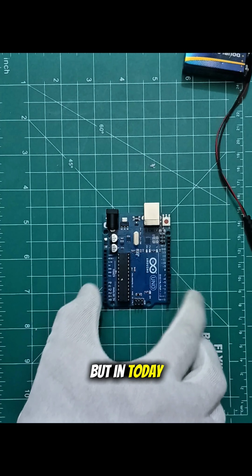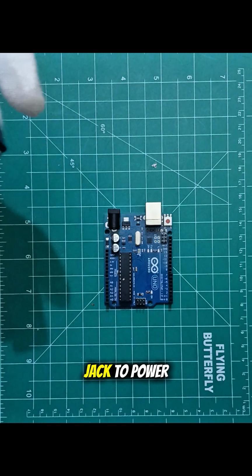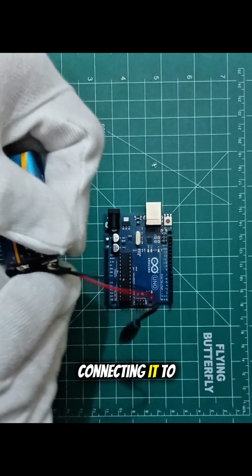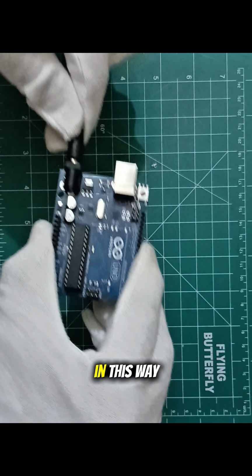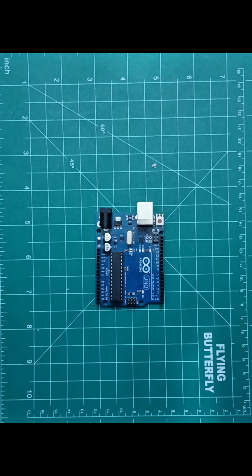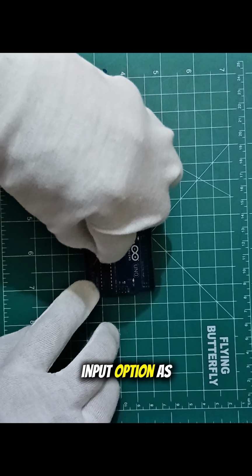But today we're going to be using this 9 volt battery and a power jack to power this Arduino. So here's the 9 volt battery, connecting it to this side, while the other side will be connected to the power jack of this Arduino. In this way we can power this Arduino. We can also use the V input option as well.